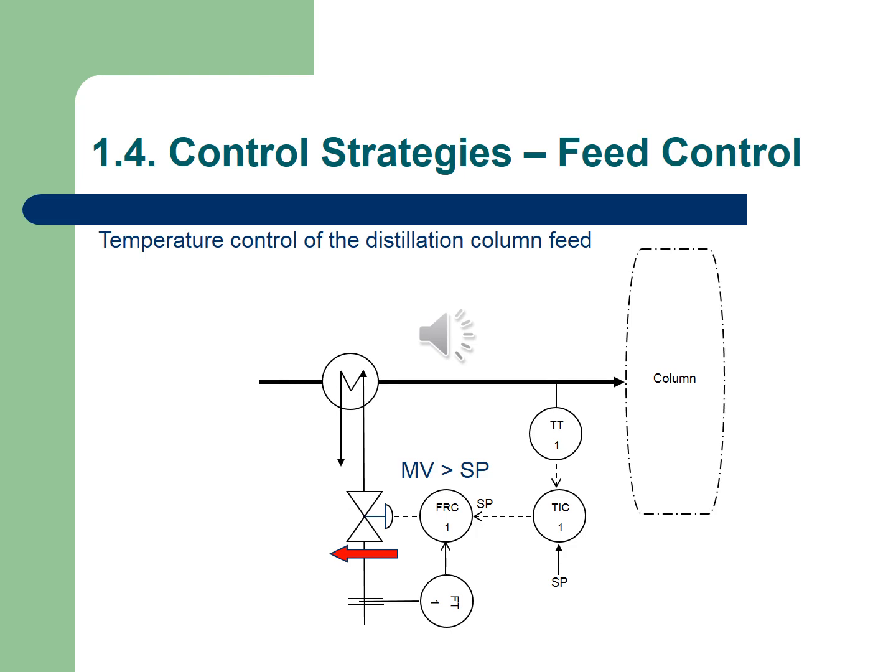Now this is the control on this. So we said that the temperature needs to be measured and also the flow needs to be measured. And this is an arrangement of a cascade controller. So the outer loop or the primary loop is your temperature, and then the inner loop or secondary loop will be your flow. And then you control basically the heating medium that goes through the heat exchanger. Okay, so you measure the amount of flow, and then you decide according to that the temperature of the feed itself that goes into the column, and we adjust just the flow through that heat exchanger.